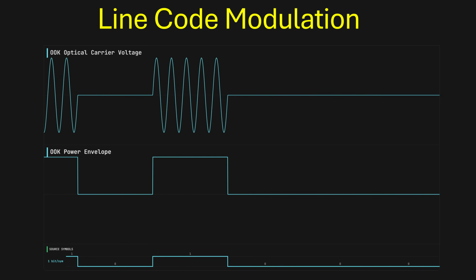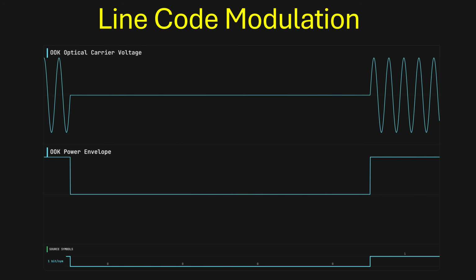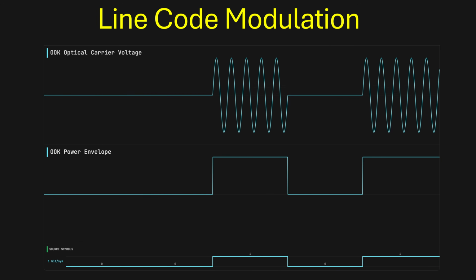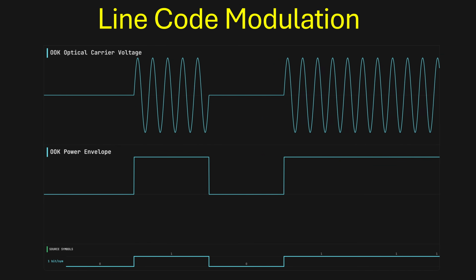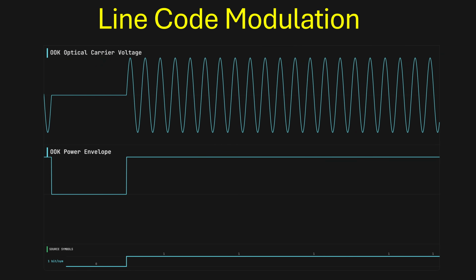For PAM and optical communications, the instantaneous voltage of the optical carrier wave cannot be directly measured. Instead, the average power from a photodiode is measured as an absolute value. So for 2 levels, it is unipolar NRZ between 0 and a maximum level, also called on-off keying.